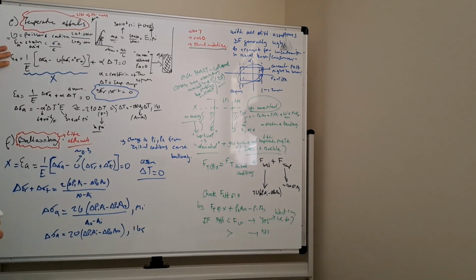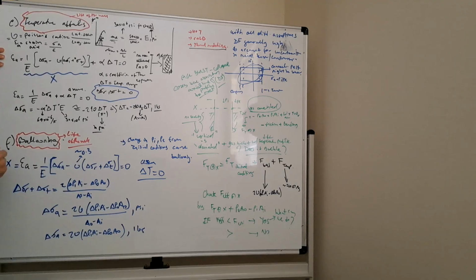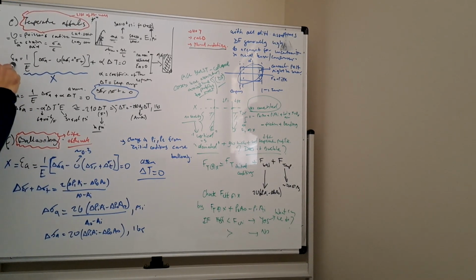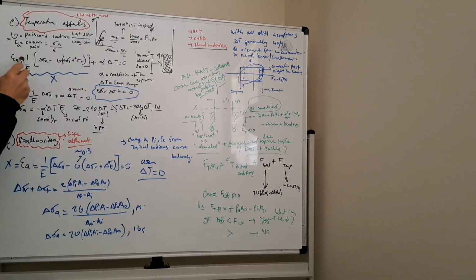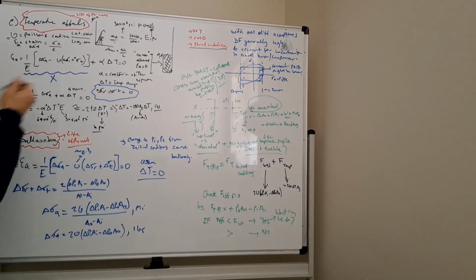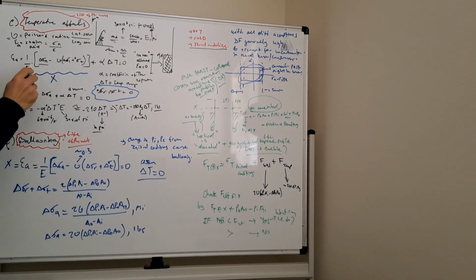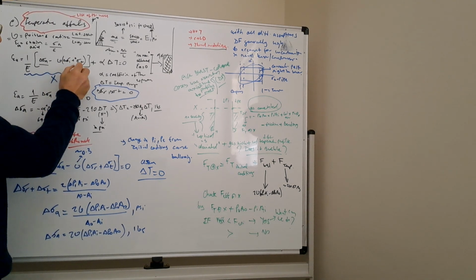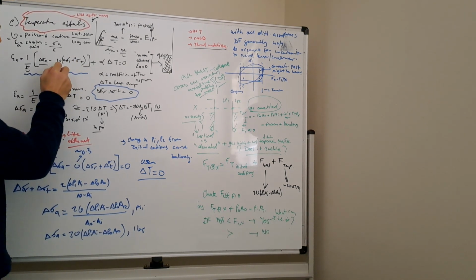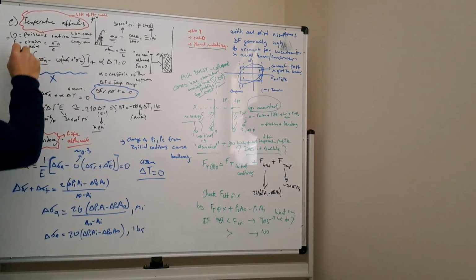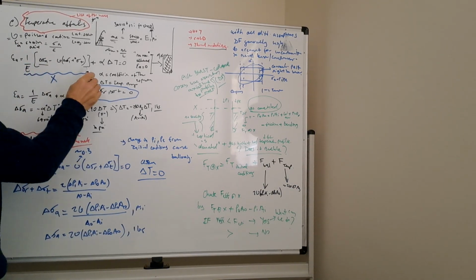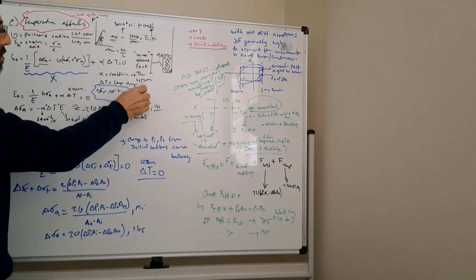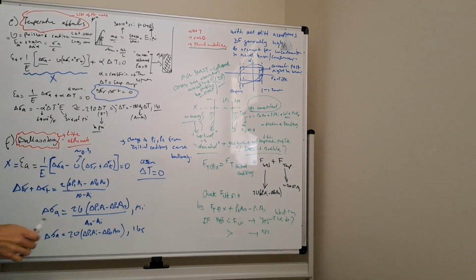So the general equation that I'm gonna use on both of them is basically this general strain equation on the axial side. So Young's modulus, that's the delta change in the axial stress, and then I have the radial stress and tangential stress change here, and then I have the Poisson ratio. Plus you can take alpha, which is the coefficient of thermal expansion, times the delta T equal to 0.